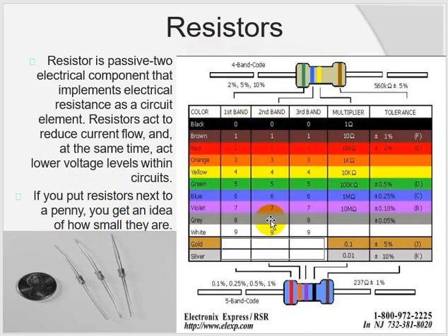And we have already studied how to measure different values by using these bands which are displayed on the body of the resistor. It could be any of the colors provided in this table, and then the first band shows the value of resistance, then the second is also the same, then the third will provide you how many zeros are placed in the calculation of the value of the resistor.